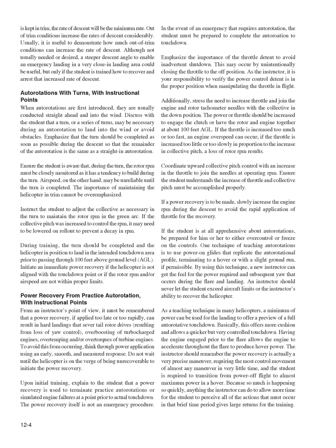The instructor should remember the power recovery is actually a very precise maneuver, requiring the most control movement of almost any maneuver in very little time, and the student is required to transition from power off flight to almost maximum power in a hover. Because so much is happening so quickly, anything the instructor can do to allow more time for the student to perceive all of the actions that must occur in that brief time period gives large returns for the training.